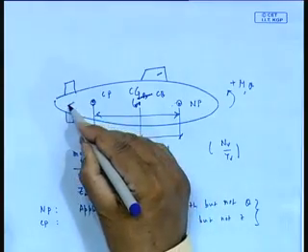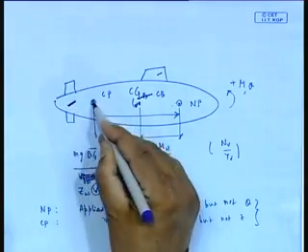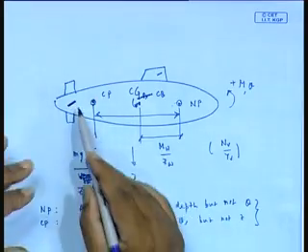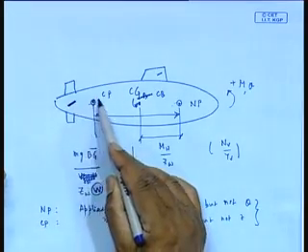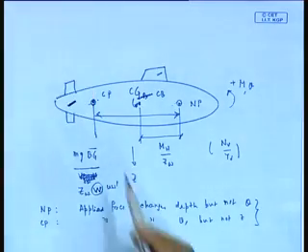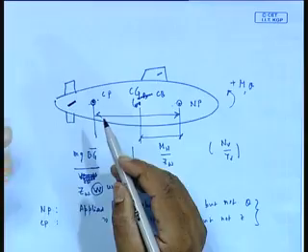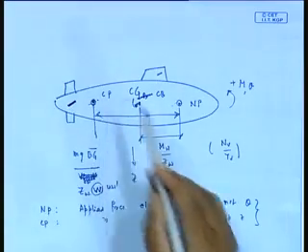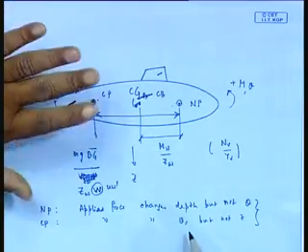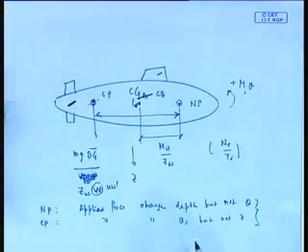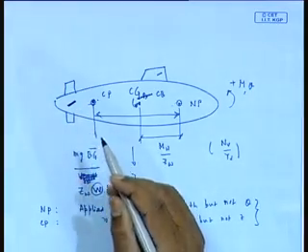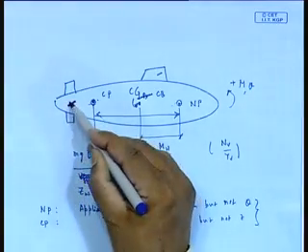Now is the interesting point. Suppose I have a stern plane located here. What would happen? Suppose my aft plane, the one that I use for changing depth, is located at this point. If I were to give a stern plane angle, I would change the trim angle, but I am not going to change depth. But my purpose of the stern plane angle is to change depth. Remember, this is what is called the stern plane angle.